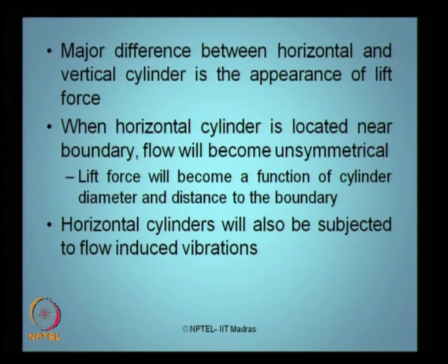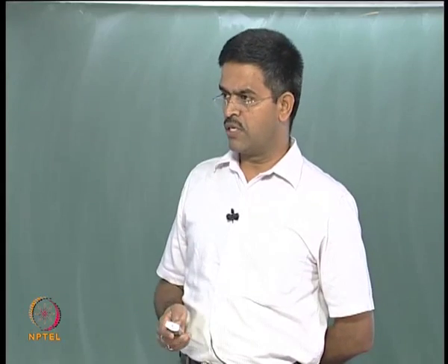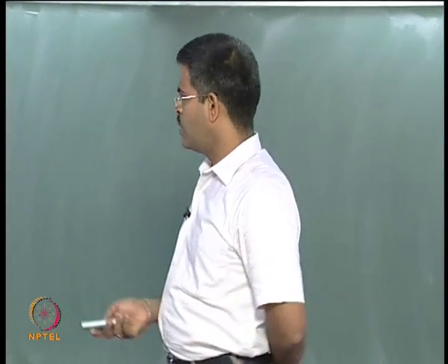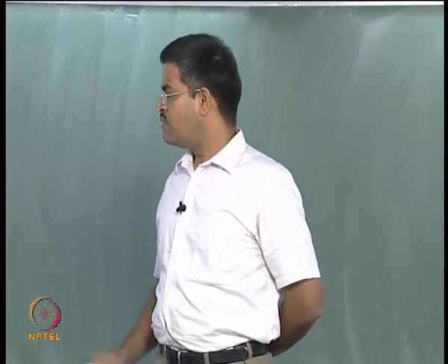In addition, horizontal cylinders will also be subjected to what we call flow induced vibration. A classical example is VIV, which is vortex induced vibration. So, they will also be subjected to flow induced vibration in addition to the inline and transverse vibrations happening because of the wave interaction.